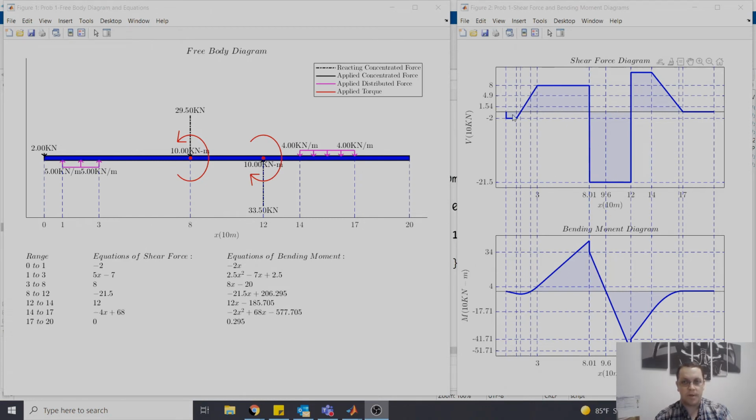There are some conserved features like this derivative that you see, the shear with respect to x. So there's a positive shear slope to this. There's a negative slope over here. So you want to be just thinking about what that has to do with the direction of the loading and all of those sorts of things. Then you want to make some additional changes. So you want to change at least one different set of support lengths.